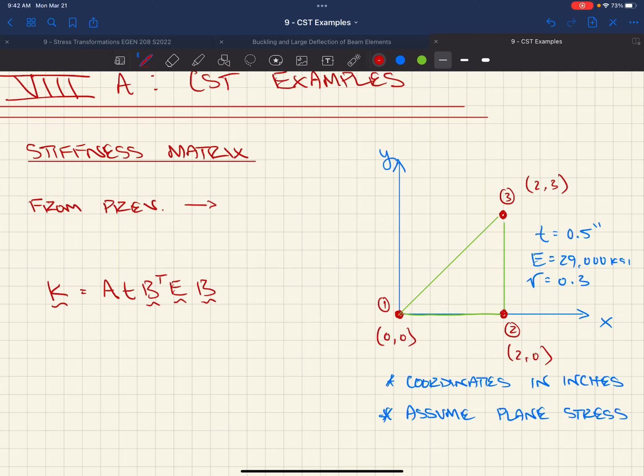Going through the process of multiplying, dividing, taking it to powers, it might not be perfectly zero. What he was talking about on Friday was that you might have a model that runs but in reality is unstable. You might run it a second time and it becomes unstable, because of the nuances of all those operations compounding over and over. That might give it some amount of stiffness when it should be zero, and numerically the program can take the inverse, since it's not singular, so you would get an answer out.